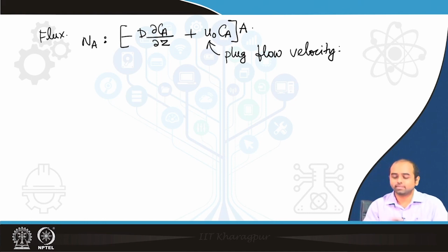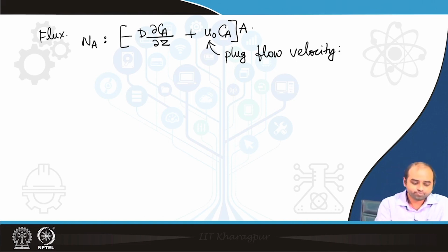So, Darcy-Brinkman is, I would say, a generalized version of Darcy's equation, which takes into account the boundary wall consideration. Since Darcy's equation is a first order model, you cannot incorporate the boundary conditions effectively, and for that Brinkman equations came into existence, where the boundary effects are very important.